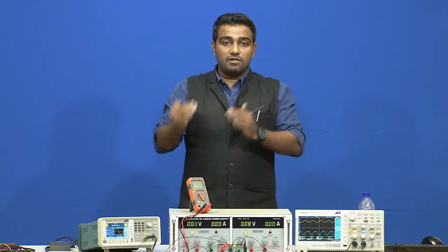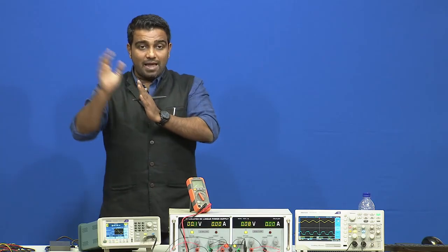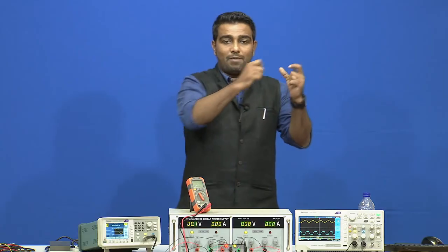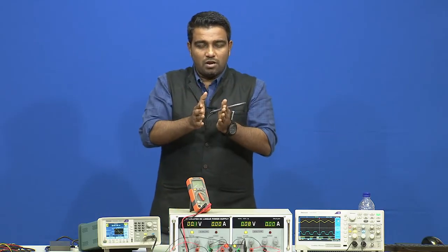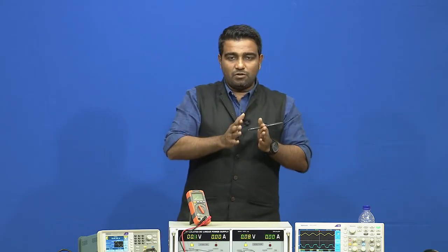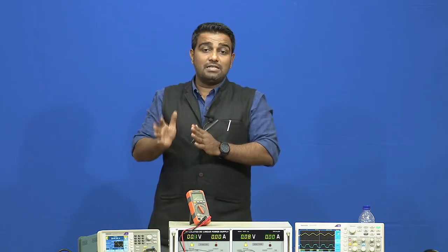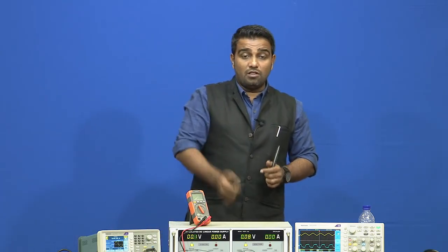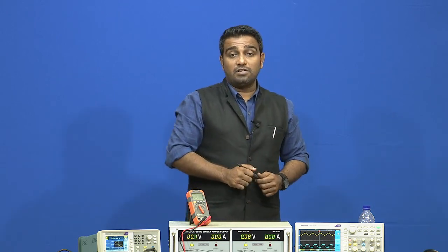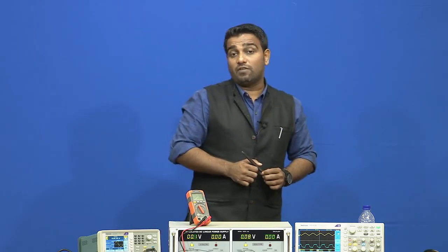The difference between the differentiator and the integrator is nothing but the capacitor. Now, instead of being in the feedback, it will be at the input of the differentiator. So, you are applying the signal to the differentiator at the input and measuring the output. In the feedback there is a resistor R, and at the input there is a capacitor C. We have a formula which we have derived, and we can see that on application of a square wave, the output is nothing but a spike in case of the differentiator, but in the case of the integrator you were able to see a different output signal.